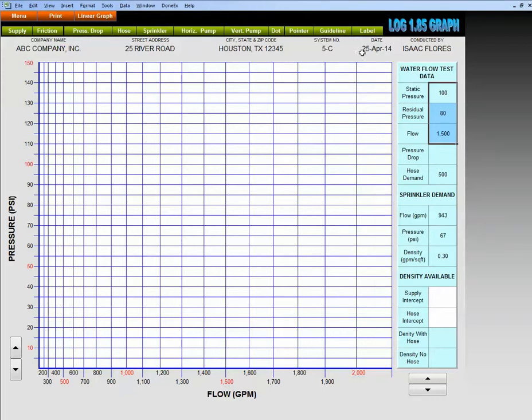Let's now bring a guideline to plot the water supply. Guideline drops into the screen and we could move it around. Once selected, we could size it. And we need to put it at 1580 to represent our water supply. So let's put it at 1500 on the flow and at 80 psi. We go to 80 psi and this represents a water supply, 1500 at 80.